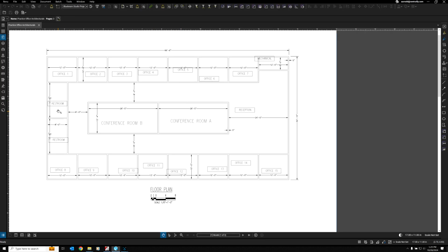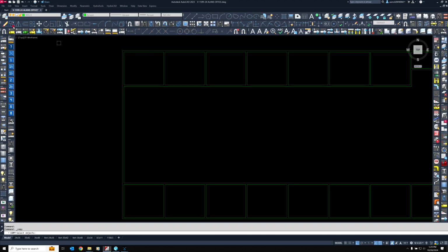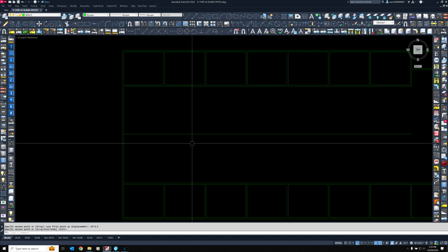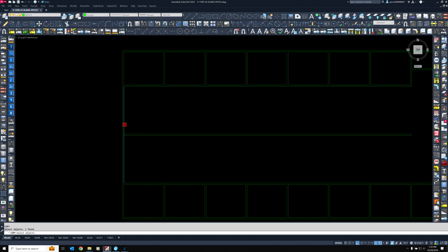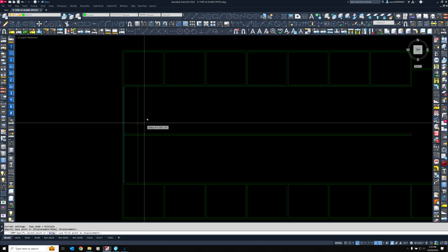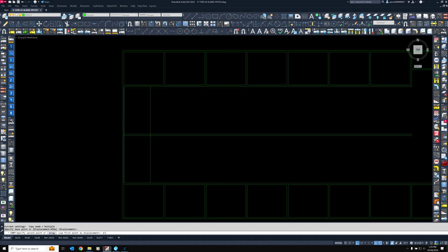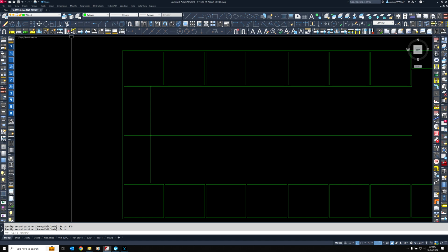Let's do a little bit, refresh. Restrooms, conference rooms, 14 foot 4.5, 5 foot between, 14 4.5. Copy, 14 4.5. Add 5 inches to that, and then grab this wall. We'll enter that copy command, repeat the copy command, left click, move it to the right, and it is 8 foot wide, and add the extra 5 feet. Let's go back to scissors.